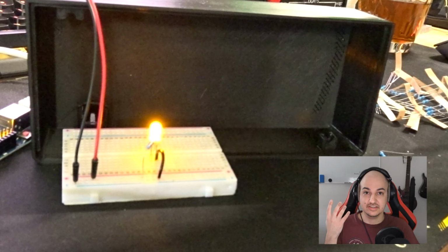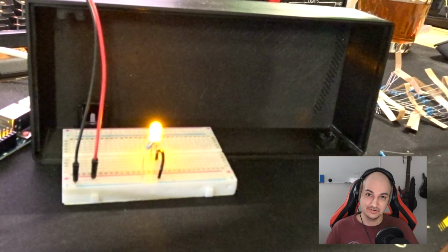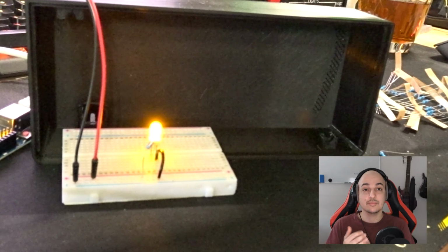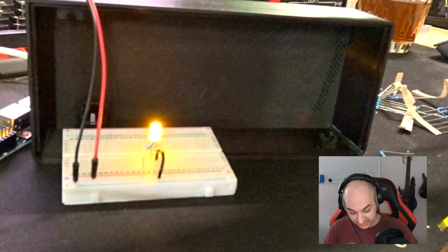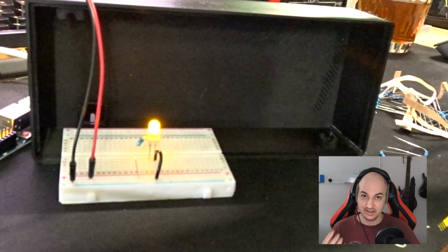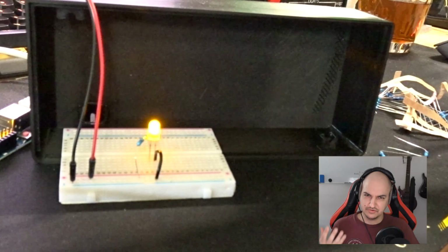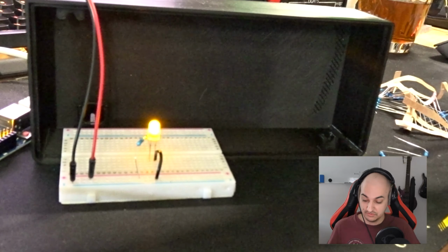You don't want it to be that distracting that you're like, please turn it off. Perhaps if you have an alarm, you really want to bother yourself, that's fine. But like I mentioned, it's a minimum value. So what we could do is that if this is a bit too bright, in my opinion, 200R, we just take it out and we add something like 500R, and this is way more softer on the eyes and way more comfortable to look at. So that's something to test around for yourself to see which one is best suited for your own use cases.